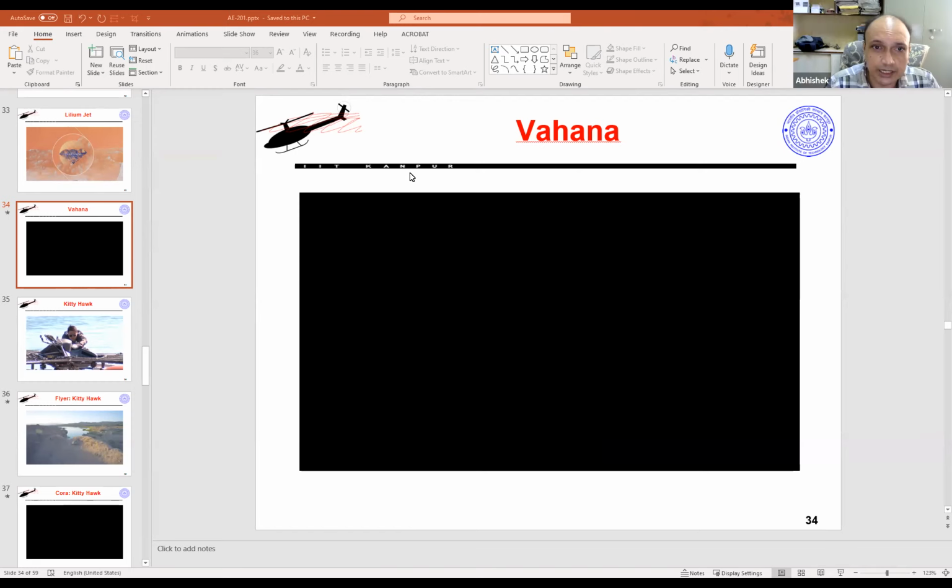The other question is regarding how to calculate pitching moment about the aerodynamic center and finding the aerodynamic center itself. All this will be covered in good detail in your Aerodynamics 1. To find the center of pressure, you need to know the pressure distribution. Center of pressure is just like finding your center of mass. All of you would have by now learned about finding the center of mass. If your mass distribution is given to you and the geometry is known to you, you simply integrate and find that. The center of pressure is similar.